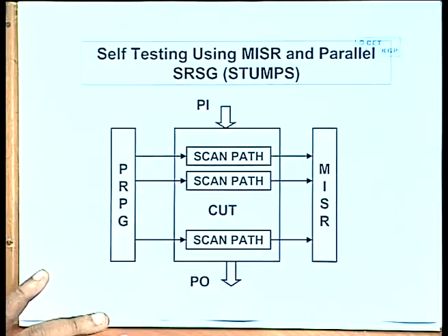This method also has been found to work pretty well, because before adopting any such method in actual practice, you will have to evaluate through simulation how good or how bad this method is, and what the implications of using it are. You will have to evaluate the fault coverage through simulation a priori, of course, before actually implementing a BIST scheme.